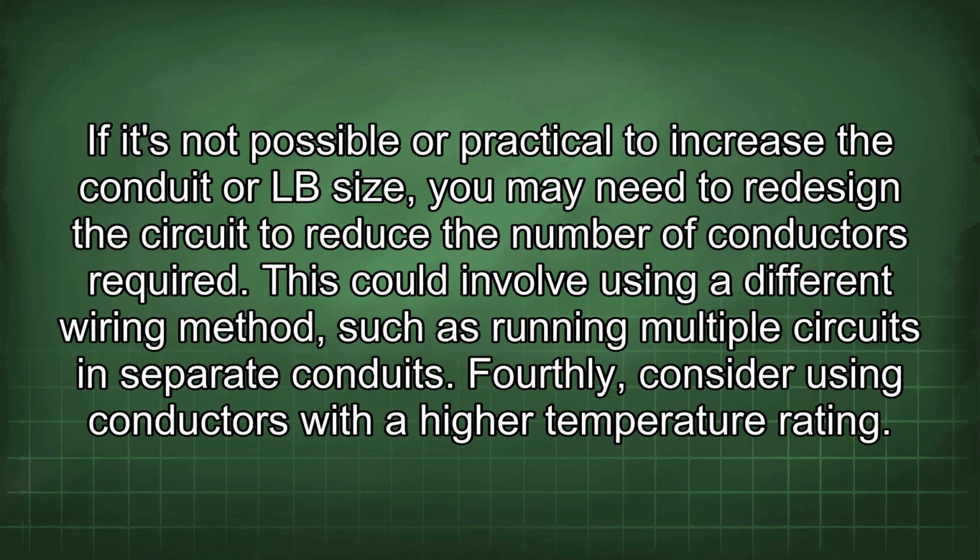If it's not possible or practical to increase the conduit or LB size, you may need to redesign the circuit to reduce the number of conductors required. This could involve using a different wiring method, such as running multiple circuits in separate conduits. Fourthly, consider using conductors with a higher temperature rating.